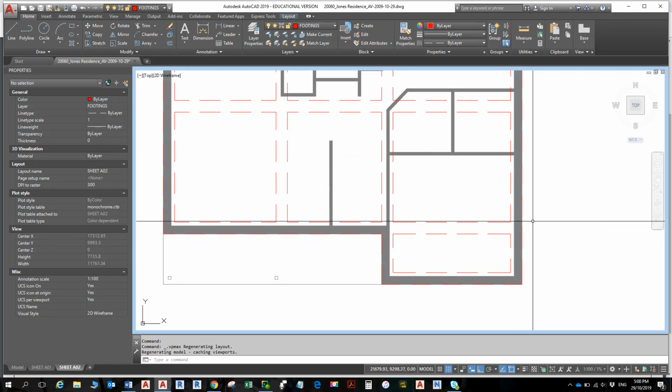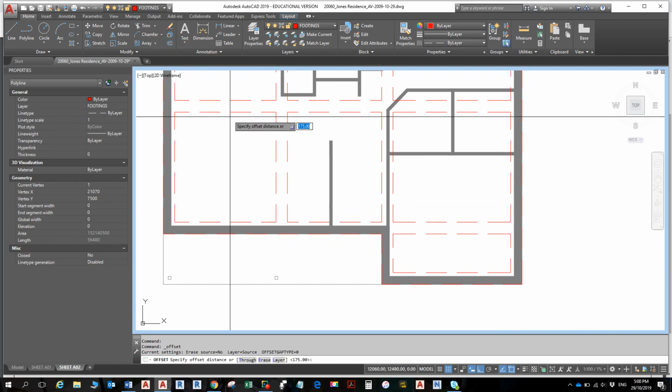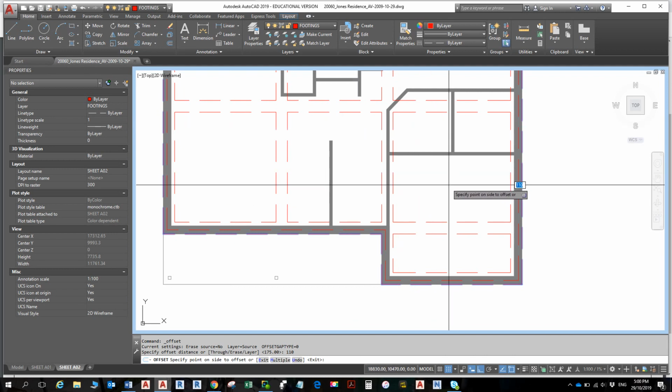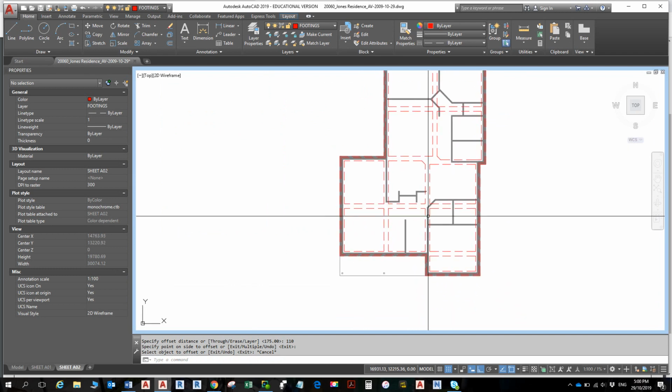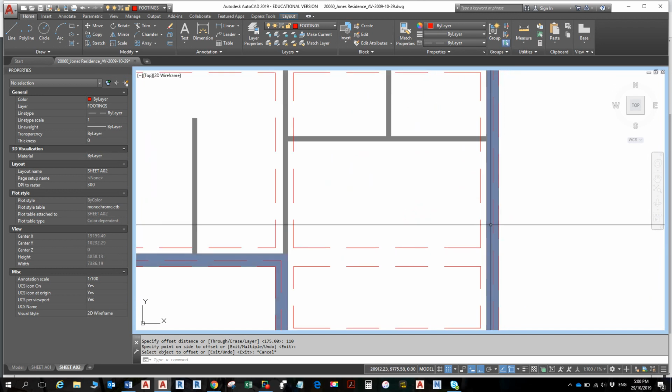I'm going to offset this line here, offset this 110. Those of you that have watched the videos from last semester, probably that's not on there. So you get caught out now. Okay, so anyway, it doesn't matter, but just showing you a bit of an improvement. So there's my rebate automatically. That polyline has been a saver around there.